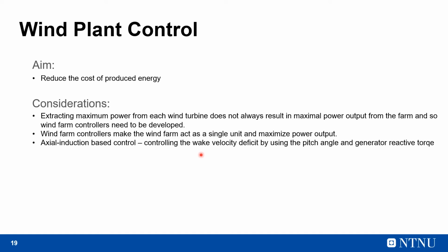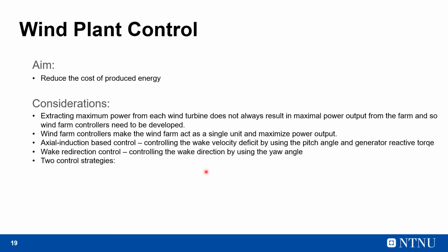If we use the control degrees of freedom to control the velocity deficit, then that's called axial induction based control. And if we use the control degrees of freedom for wake redirection, then it's called wake redirection control.